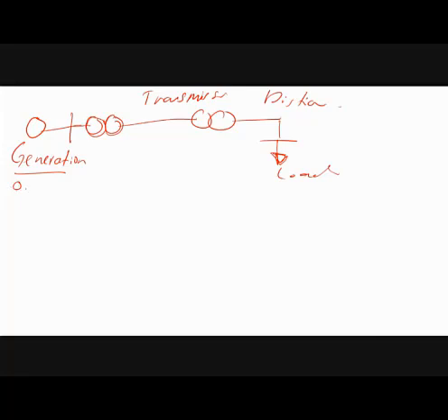up to 20 kV, and then we will step up this voltage, let's say from 20 kV up to, in Malaysia, the maximum transmission line voltage is 500 kV, and then we will step down this 500 kV towards maybe around 33 kV before we step down further from 33 kV to 11 kV at the distribution center.